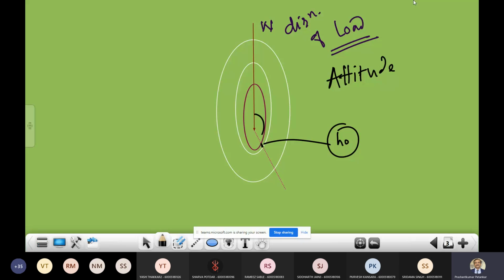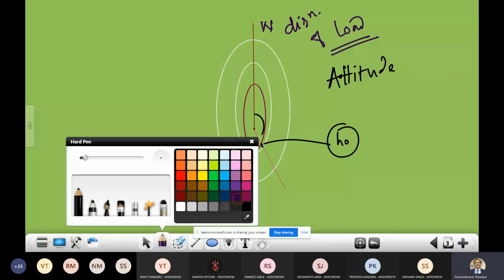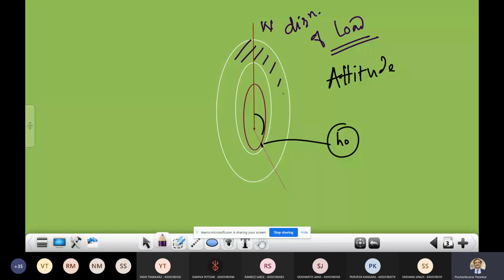the attitude angle. Now in this particular figure, what do these outer two white ellipses indicate? Can anyone tell me? These outer two ellipses are nothing but our bush, our bearing. The circle or ellipse shown at the center is your shaft.